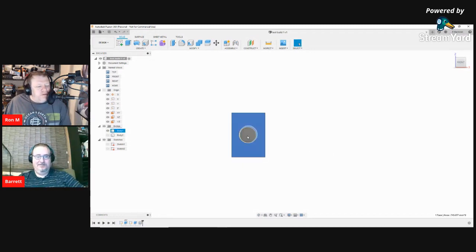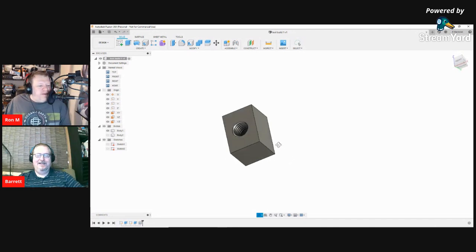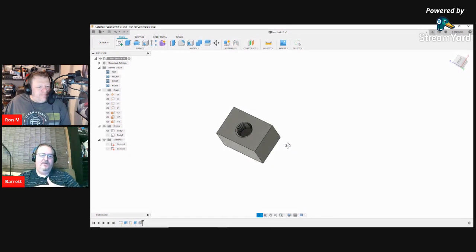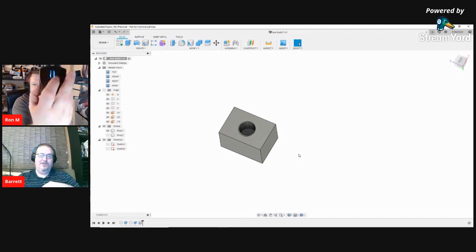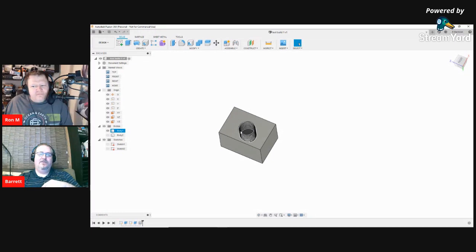Oh, come on. I'm selecting you to move. It doesn't want to move. Shift and middle mouse to orbit. Oh, shift middle. Yeah. Most professional CAD software uses the middle mouse button, which on modern mice can be a real pain because it's also your scroll wheel. So that's your middle button right there. Your scroll wheel is your zoom.